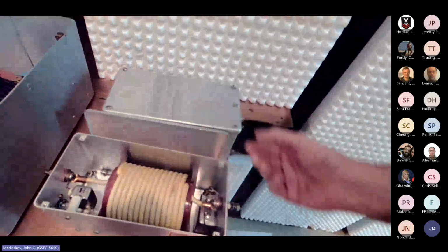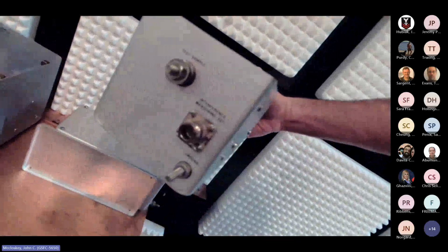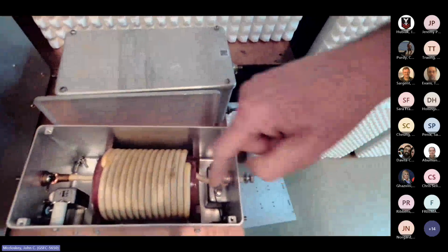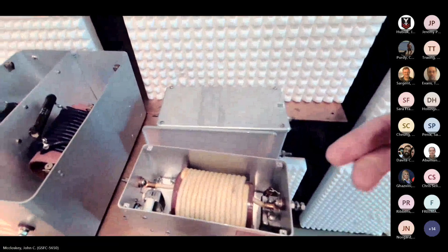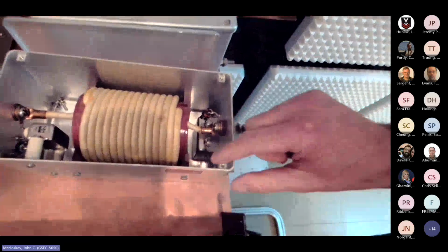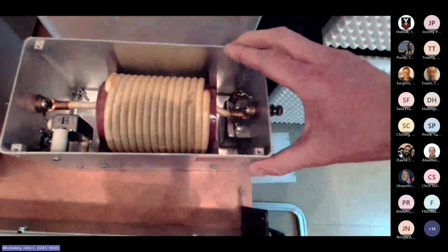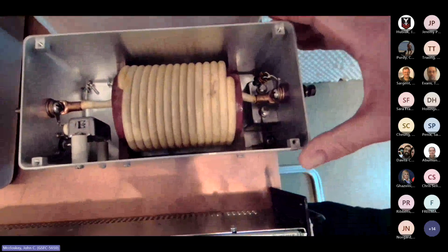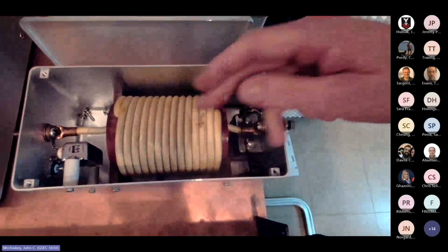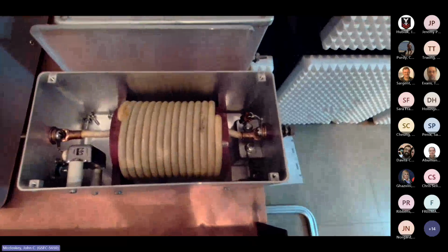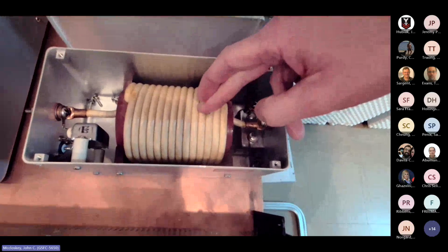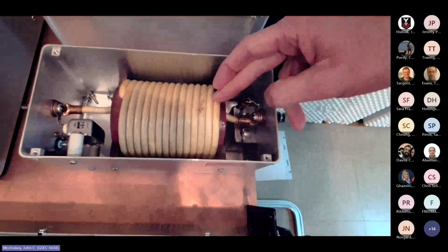So the 5 microhenry LISN, again with the measurement port over here, where you would connect up to your EMI receiver or put a 50 ohm termination on there. And then it's got a couple capacitors and resistors. But the 5 microhenry inductor is the business end of this thing. Still trying to get the feel for pointing this camera. But here again, here's my hand. 5 microhenries is also something you don't get by accident. 50 microhenries is very much something you get by accident, but 5 microhenries is still something you have to get on purpose. This is what you have to do to get 5 microhenries.